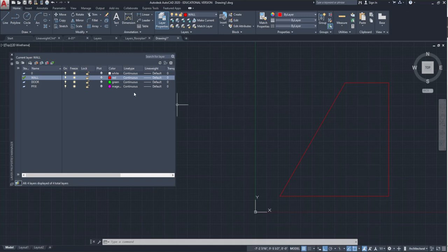I should have used a polyline to create this so it was all one. But I'm going to use the offset tool, OFFSET, enter, which we talked about last week. 6 inches, enter. Click, click, click, click. See, I should have used polyline because now those won't connect. Don't worry, we'll learn how to fix that. Click, click, escape, escape, right?